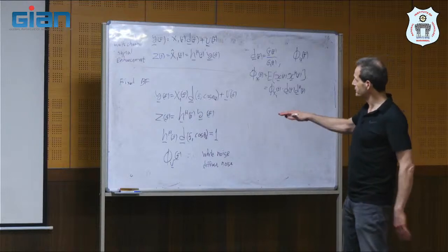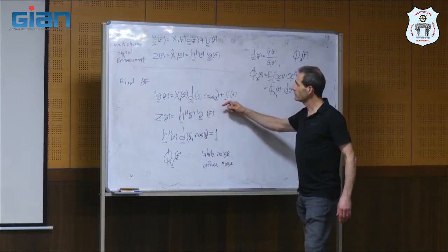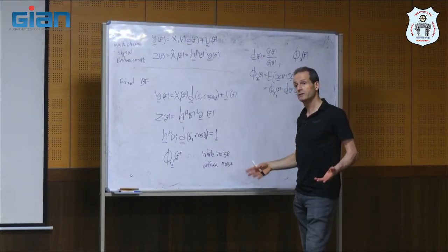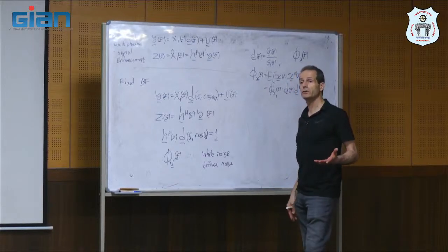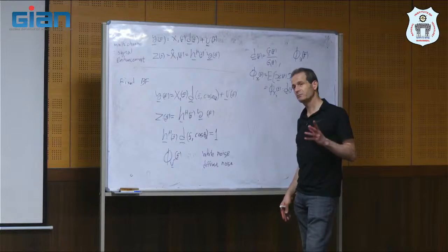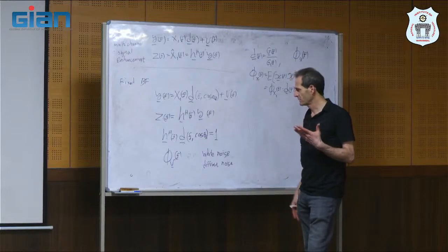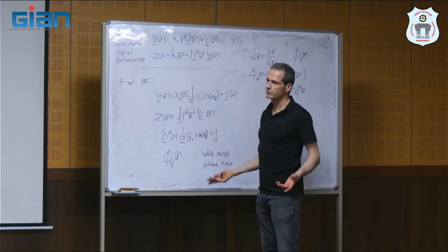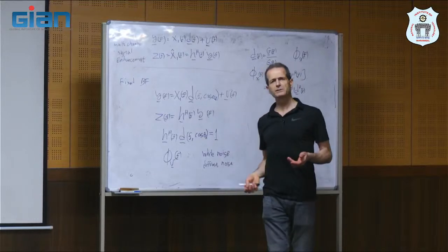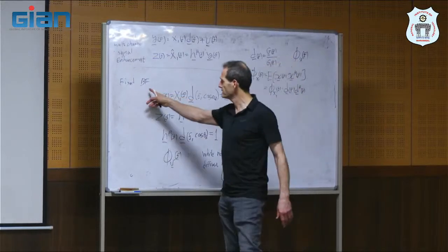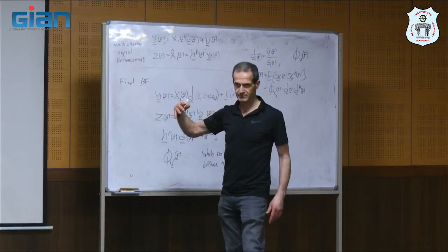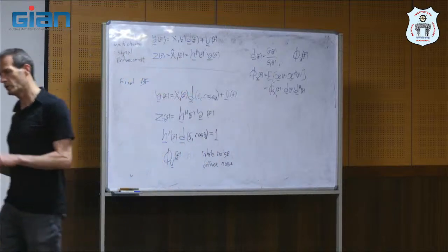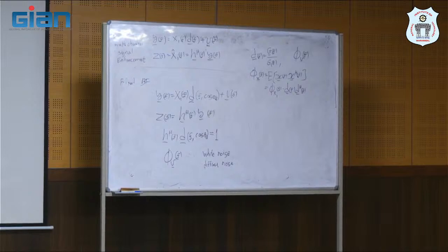Once we understand these differences, now we can take the solutions that we did here to here. But the performance measures, can we define mean squared error? Actually, we cannot define mean squared error because it's irrelevant. Because we don't know the signal. We don't know the variance of x1. So we need to define performance measures and find optimal fixed beamformers based on this information. Okay? This is the most important thing, to understand what is the problem, what we know, and how to proceed. Any questions?